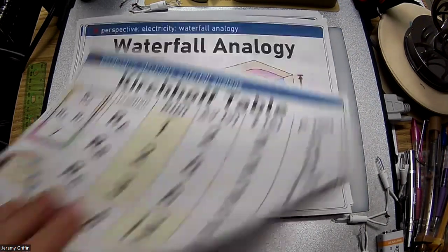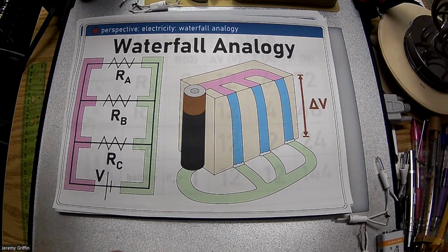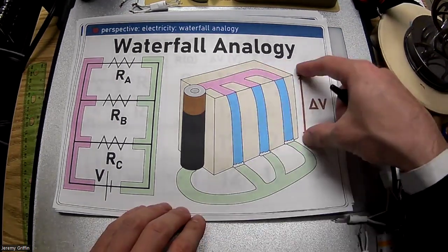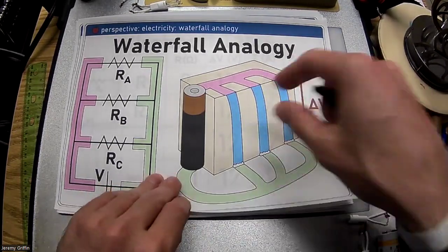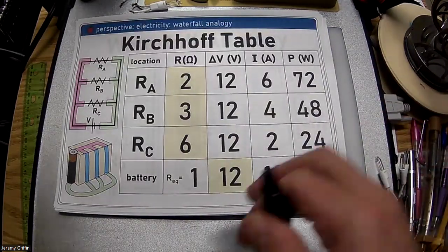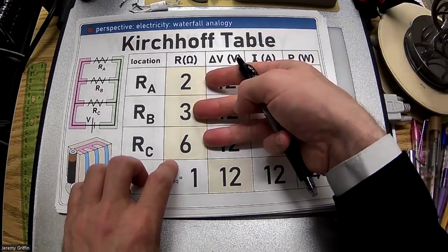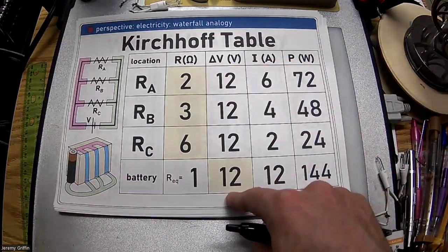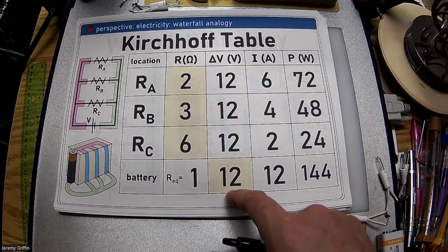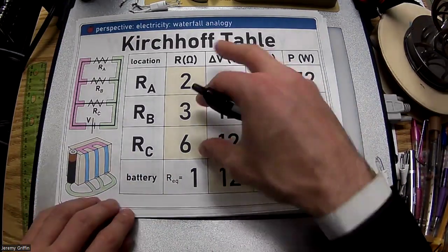Okay, here's good. All right, let's look at a parallel setup. Here's parallel. Now this one, you know the voltage drops are all going to be the same because they're all in parallel, even if the resistors are different. So same as before, I gave you guys 3 resistors. Those are the gold boxes. I also gave you a 12-volt battery.